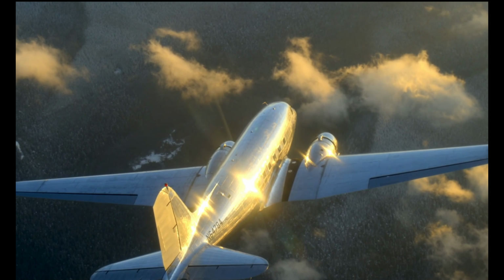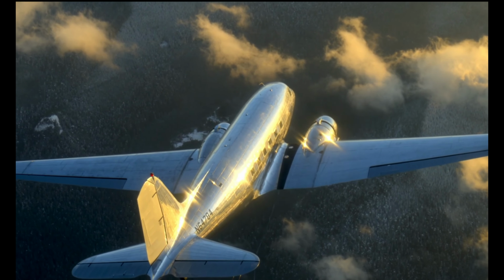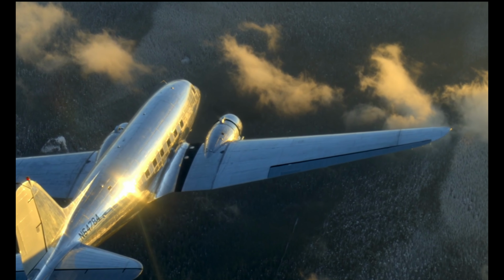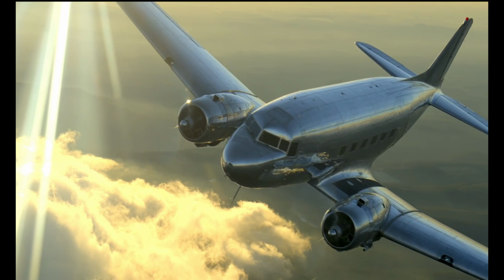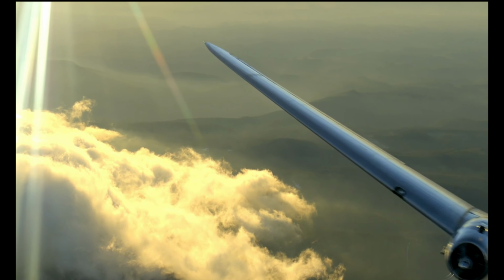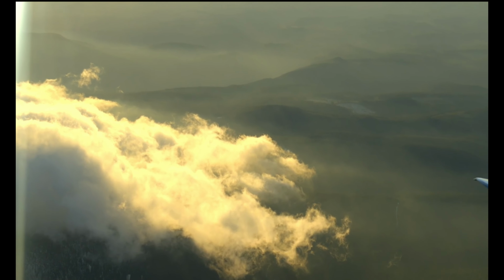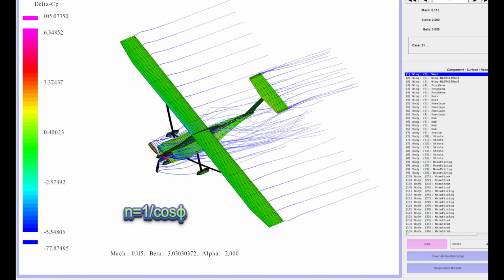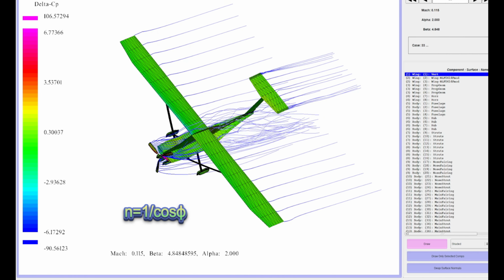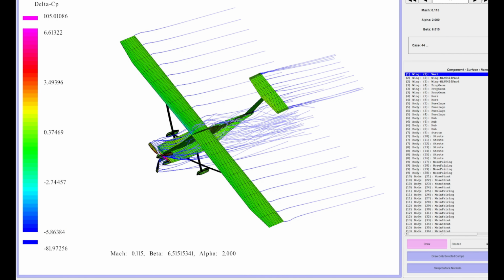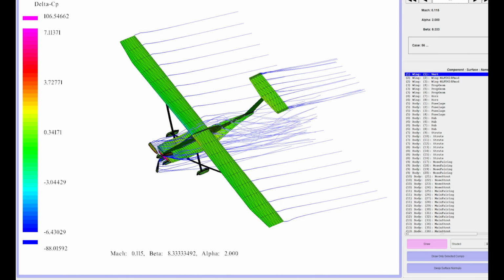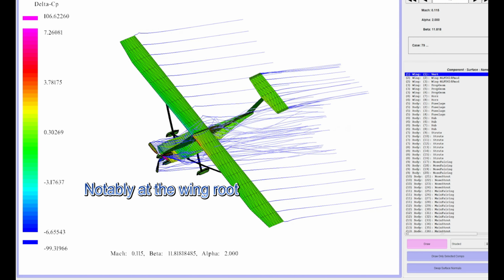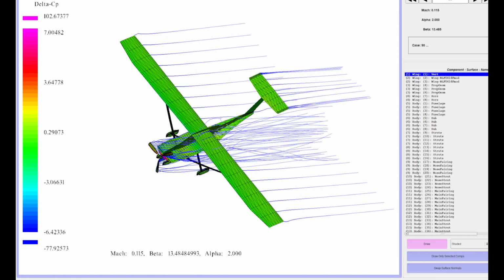From the turning speed formula, a series of calculations can be carried out to obtain the corresponding turning radius and turning time. Here, the minimum equilibrium turning speed can be determined using the balance equation. When looking at the turning load factor n as the turning speed increases, even a small increase in bank angle can significantly raise the load on the wings. This means that the maximum speed must include a sufficient safety margin.